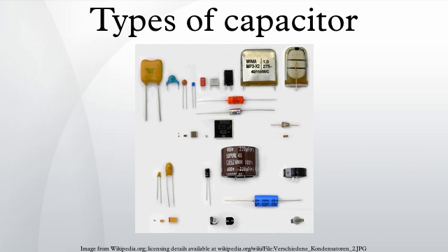Three general types of electrolytes are used: non-solid, conductivity approximately 10 mS/cm, which are the lowest cost; solid manganese oxide, conductivity approximately 100 mS/cm, which offer high quality and stability; and solid conductive polymer, conductivity approximately 10,000 mS/cm, which offer ESR values as low as less than 10 mΩ. Internal losses of electrolytic capacitors, prevailingly used for decoupling and buffering applications, are determined by the kind of electrolyte.